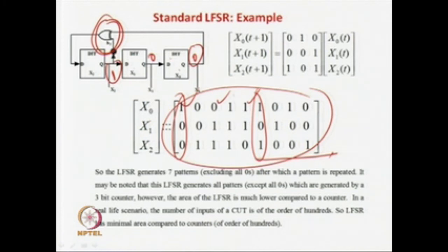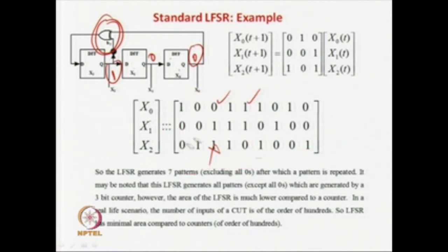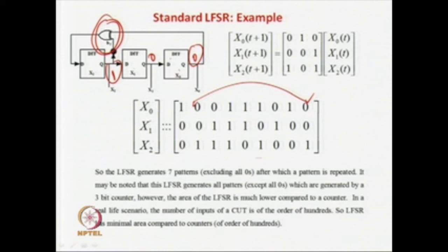But say that this set of patterns is important for you, excluding this one and so forth. You start with this seed, so very quickly you will get this coverage, the important set of test patterns, and you can stop. Similarly, if you have some other important test pattern, say this one, here is also a repetition, you can see there is a repetition over here. Up to this only, after that it repeats.